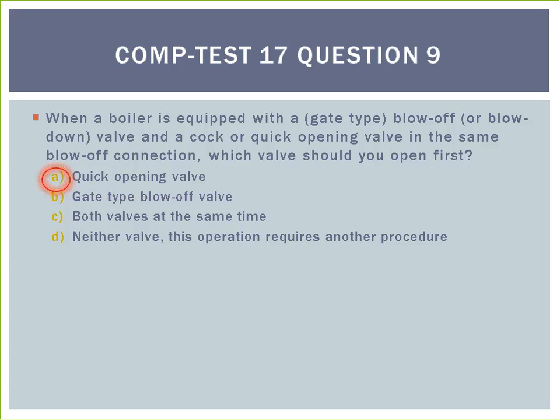Note, never pump the quick opening valve to blow down the boiler. Such action could cause water hammer and damage piping and valves. It could also cause personal injury. Never leave an open blowdown valve unattended. Remember, the valve closest to the boiler must be open first.